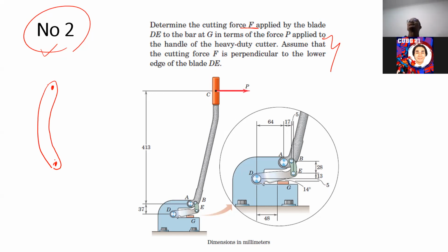And how can we represent the force there? The force there is supposed to be the straight line between those two joints. So if it's under tension, it's supposed to be like this. If it's under compression, it's supposed to be the other way around. Rafi, do you get it, Rafi?